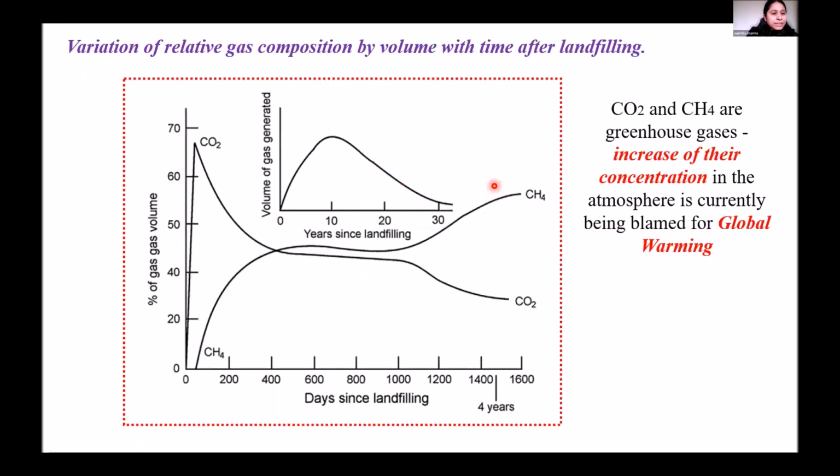Now, this is another interesting slide which talks about the age of the waste, which affects the generation of carbon dioxide and methane in the landfill. And it has been seen that the age of the waste affects the oxidation reduction, pH, and other important characteristics of the landfill municipal solid waste which is deposited here. So the physical, chemical, and biological conditions of the landfill are the governing parameters which determine the rate of degradation of the waste. As you can see in the slide, this is a characteristic study, and it's not from India. This is information that I got from Dr. Valero, who has published this data.